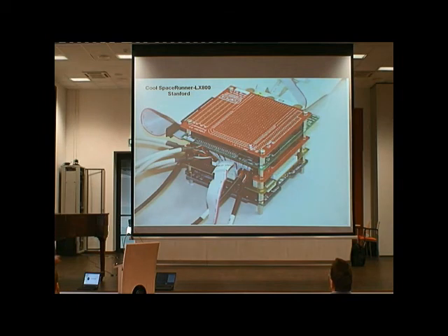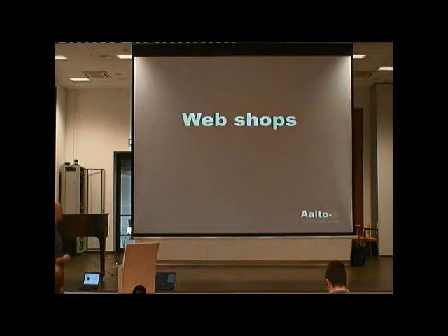A stacked configuration, stack-through bus, and sort of modular design where you have all your modules. But make no mistake, this is not part of the CubeSat standard. This is a de facto industry standard, so you can go to the web shop and buy a radio according to this standard, or reaction wheels according to this standard, or even a camera or something. But this is not the CubeSat standard. A CubeSat can be whatever it wants from the inside.